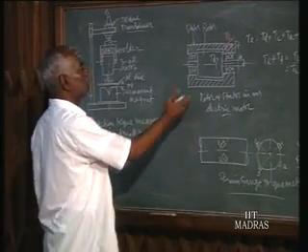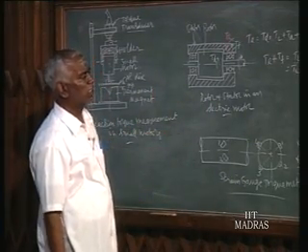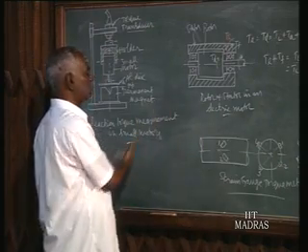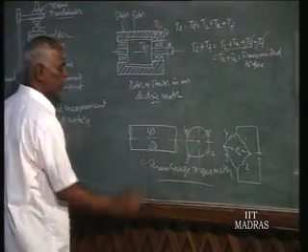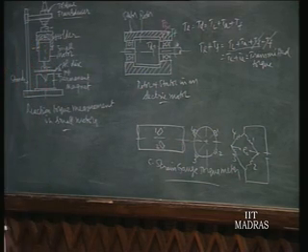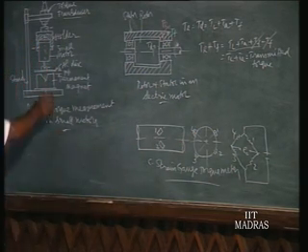So this is the second method. The first method is the transmission dynamometer. The second method is the reaction principle. The third method is strain gauge. This is method C, strain gauge torque meter. This is also widely used in shafts. The reaction principle is used only in small motors.